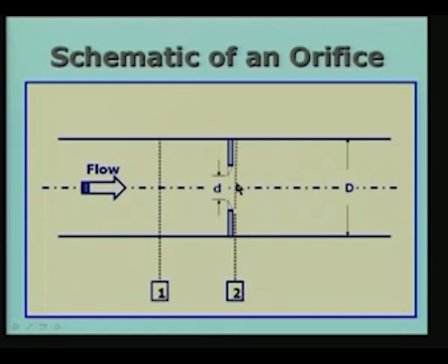Now, we can choose two locations 1 and 2. In this case, I have taken one upstream of the orifice, usually one diameter away from the orifice, ahead of the orifice, and the second one I can choose very close to the orifice like what I have done. There are different ways of doing it which we will come to a little later on.